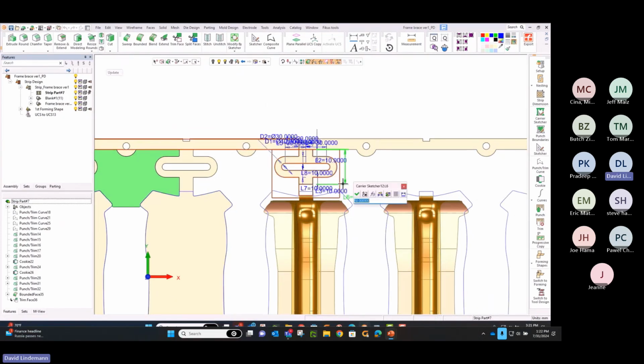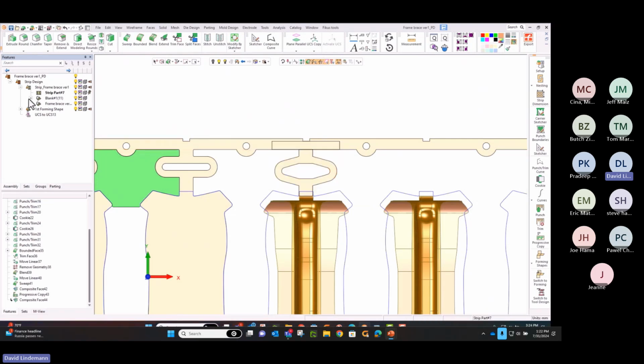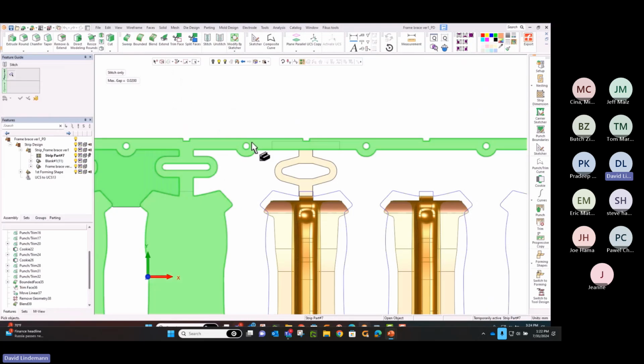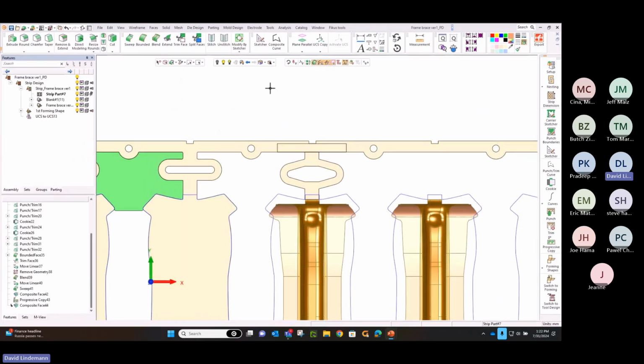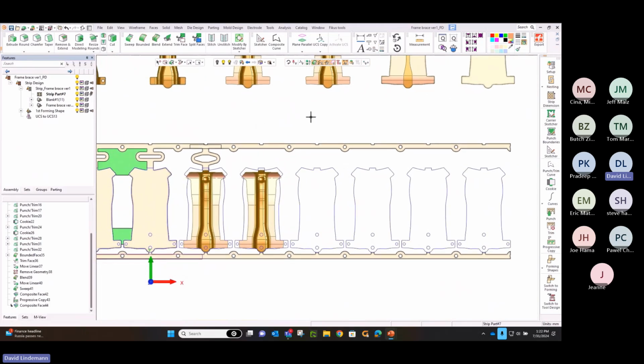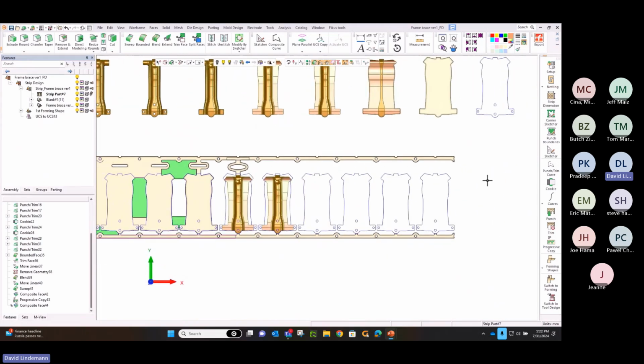Now I'll edit the dimension, and simply I could have taken the measurement to see how much the gap is. We'll open it up by that difference, which is going to be 12 mil. So adjust the 50 mil to 62 mil. Okay. And there I've opened it up so that it shows me what that would look like. And that's important. I need to know where that metal is going to be if I'm going to do anything around that area, right? Even if I'm just going to use a lifter or my cutoff.